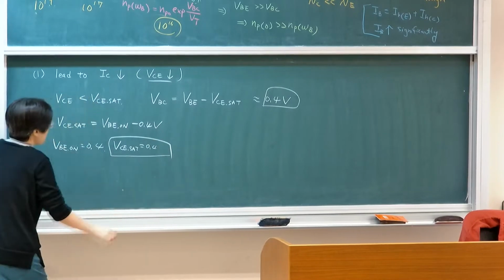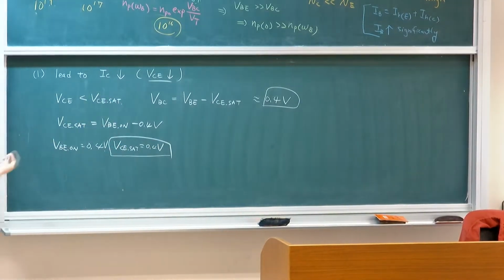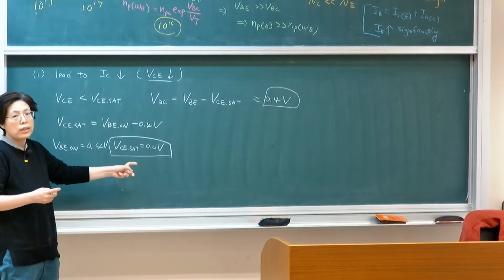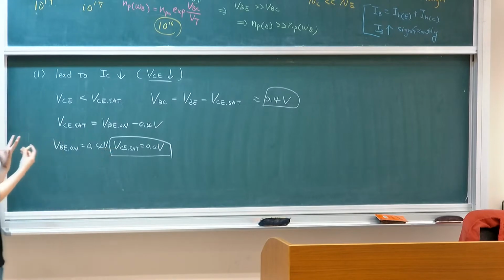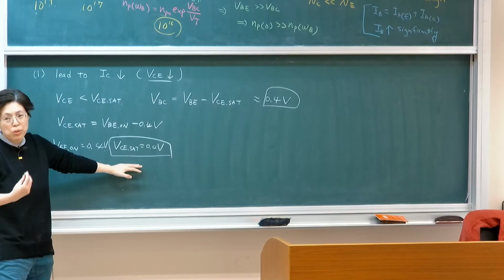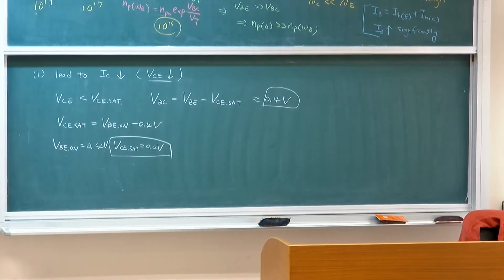So this will also typically be given to you in the question. These are also device parameters that will be given to you. VBE on and VCE on are both limiting where the operation region is. This is typically what we use to define whether it's in active or in saturation in circuit analysis, not describing what really happens in the device. So this is typically referred to as circuit saturation, when you see the difference in collector current. Okay?